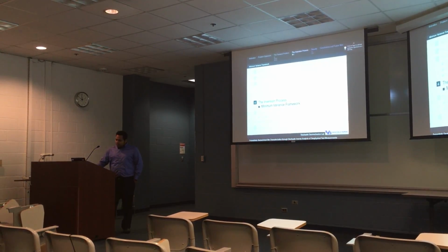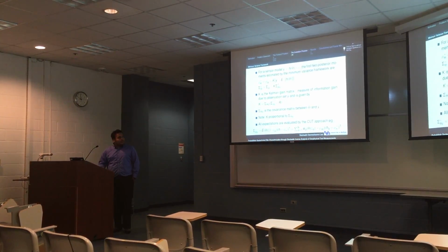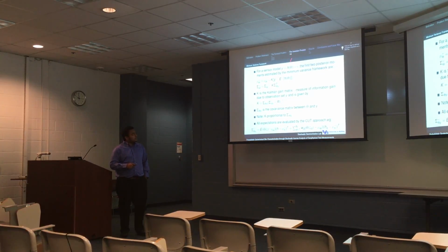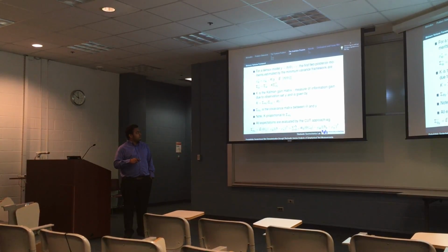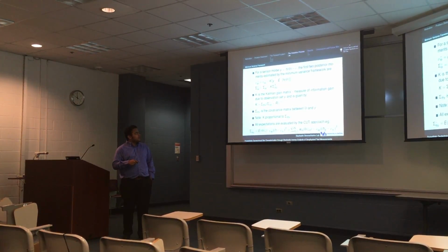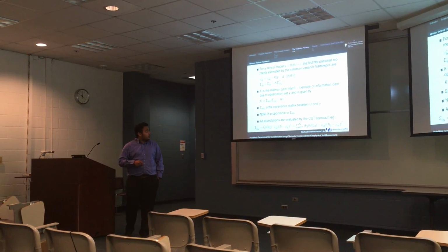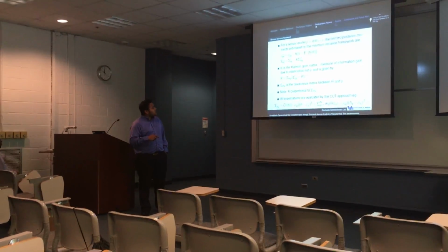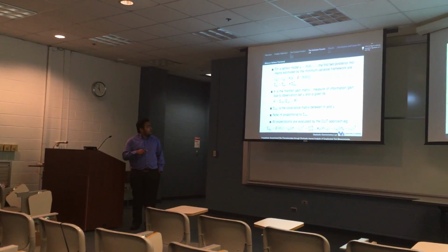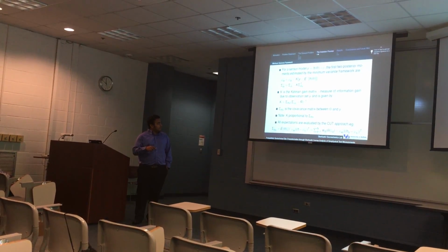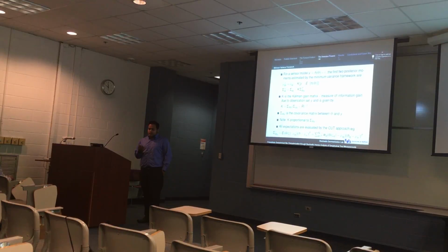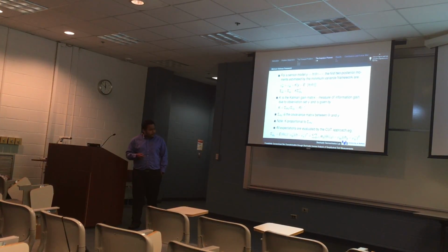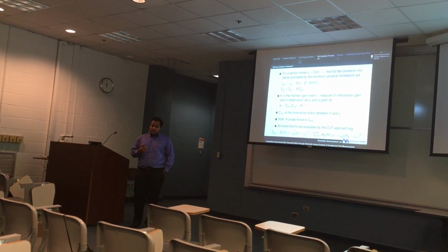Okay, for the inversion process, we go for the minimum variance framework. For a sensor model Y, where h of theta is the true measurement and mu is the measurement error, the first and second order moments are given by these two formulas, where K is the Kalman gain matrix, and it is a measure of how much information this measurement Y has given us.